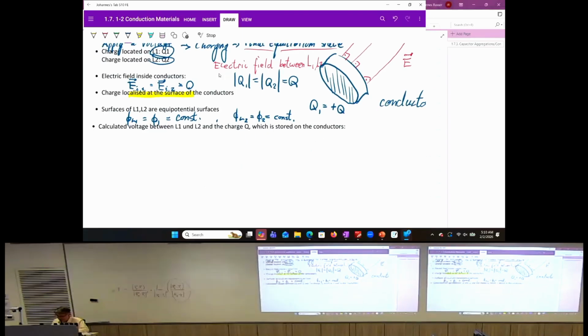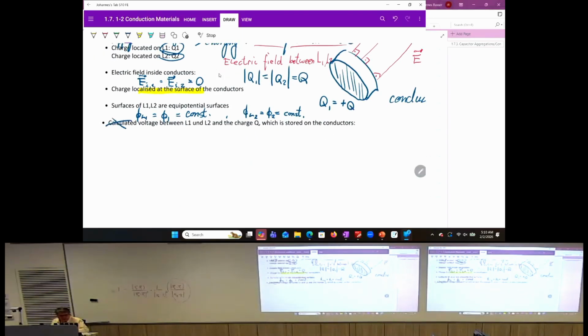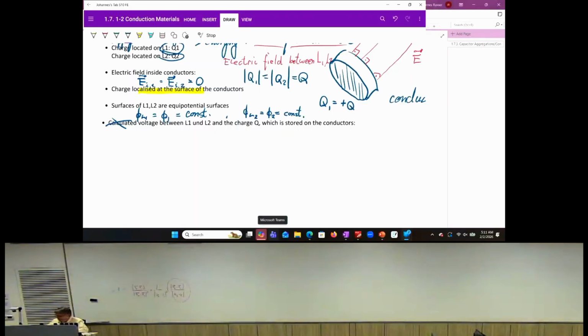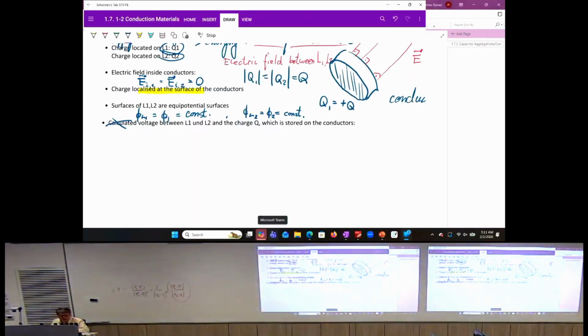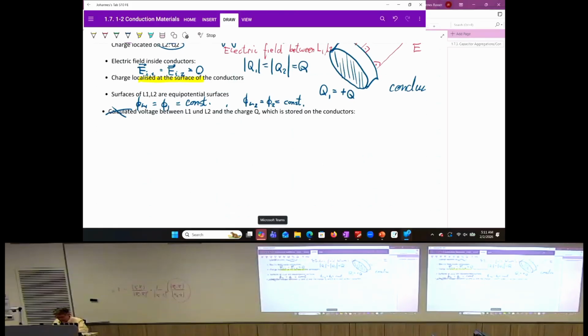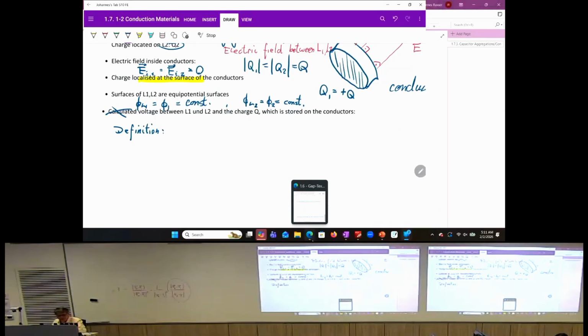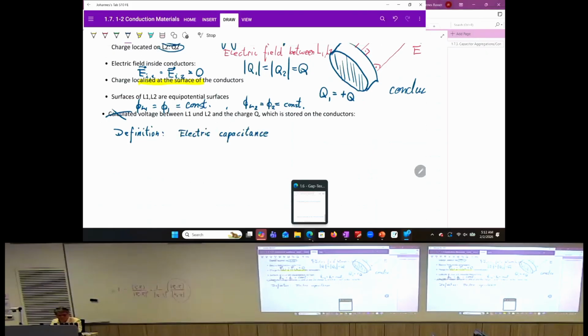We, however, want to get now the definition, basically, of the capacitance. So you have applied a voltage to these two conductors, so charge has flown onto these, and I mean, they exert a force on each other. In consequence, you have the electric field in between these two conductors, and the whole arrangement accounts for a capacitor. We can give a definition of the electric capacitance.